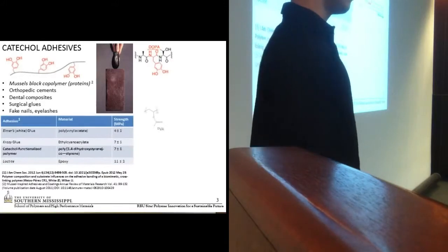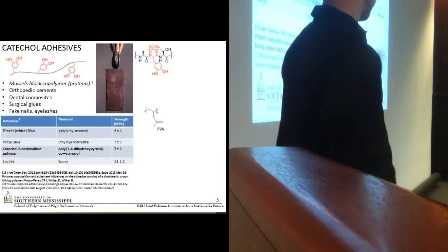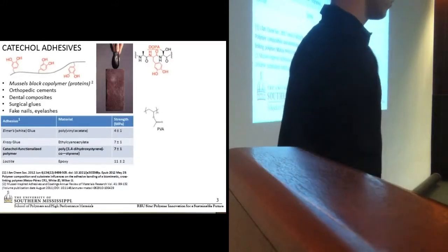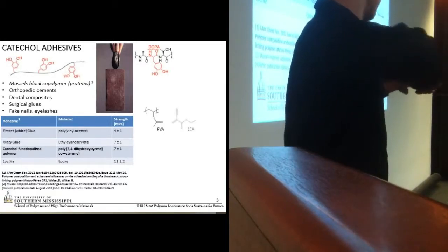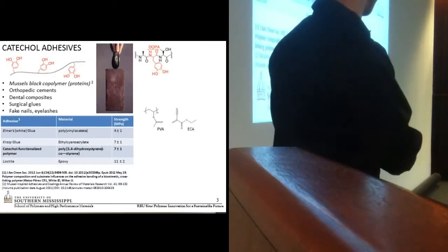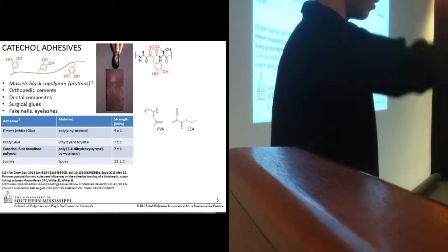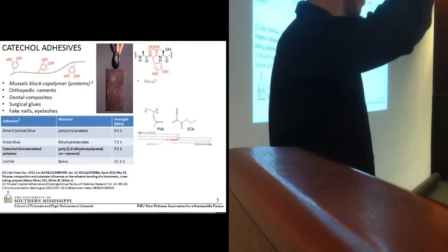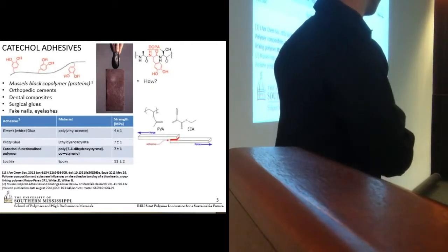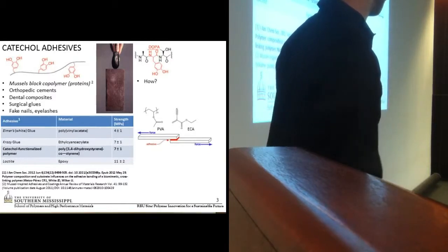How did they test this? They used lab shear adhesion testing, which you'll see here in the diagram. You have two surfaces pulling apart from each other. And this pressure here is calculated by dividing the force at which it ruptures by the contact area.